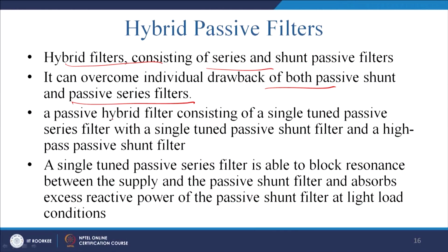The passive hybrid filter consists of a single tuned passive series, a single tuned passive shunt and a high pass passive shunt filter. So, many combinations are possible.